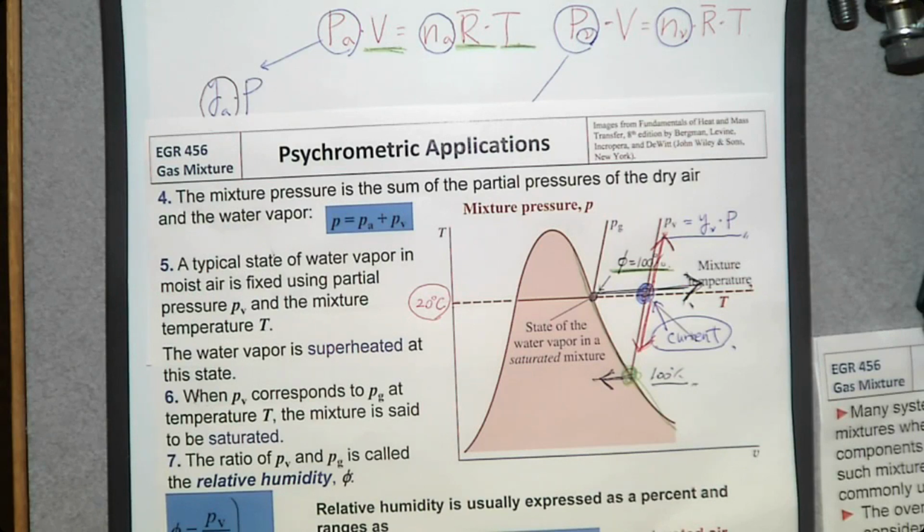So turning the heater on does not help a lot, but you need to turn on the air conditioner so that you can remove the amount of water, because the air conditioning system removes the water. That's what you can study later, when we talk about dehumidifiers using air conditioning systems later in this chapter, okay?